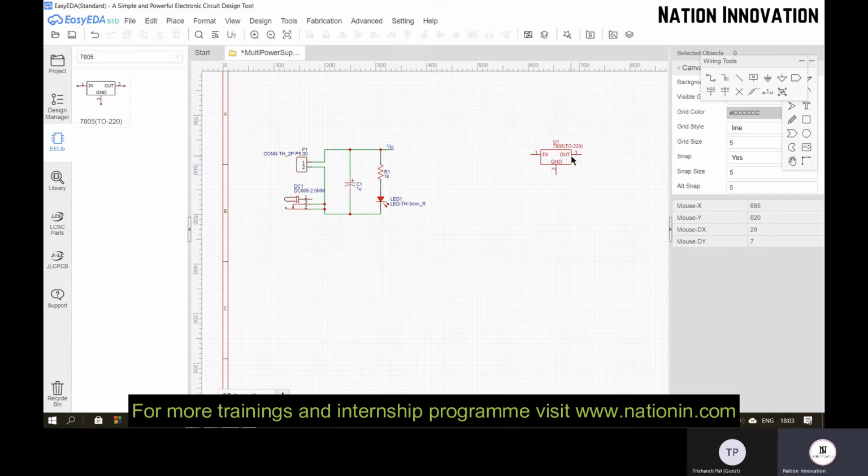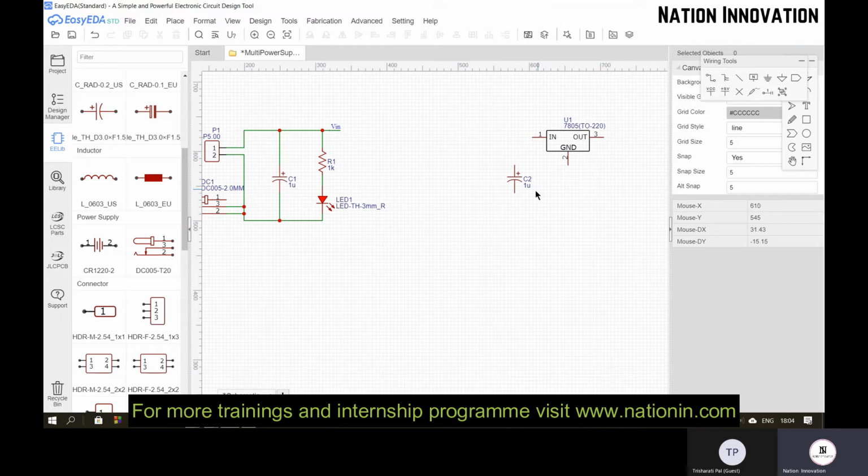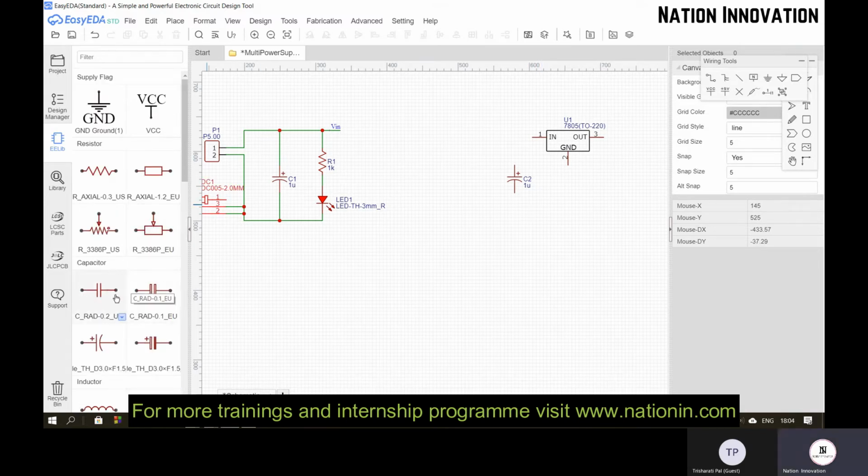And again, for this voltage regulator, we are going to connect two more capacitors. The capacitor will again do the filtering here. So firstly, I will connect an electrolytic capacitor. So why electrolytic means the capacitance of electrolytic capacitor will be somewhat high as compared to the ceramic. So these are our ceramic capacitor. For smaller capacitance, we go for the ceramic like 0.01 microfarad and for the higher values of capacitance, we go for this electrolytic capacitor.